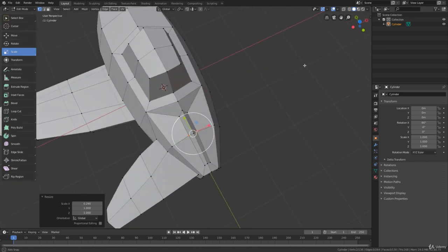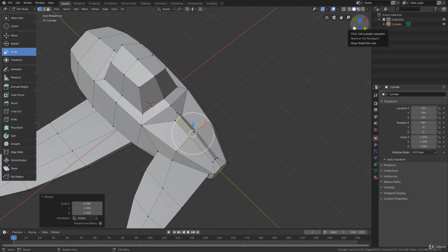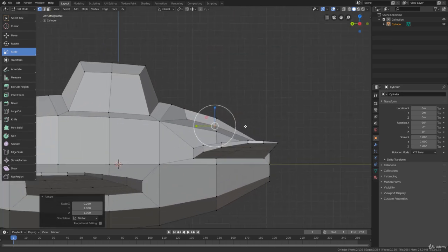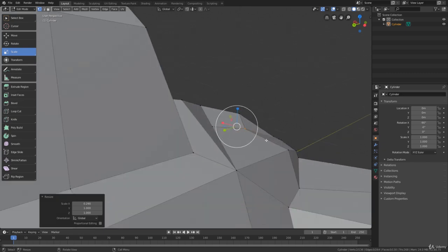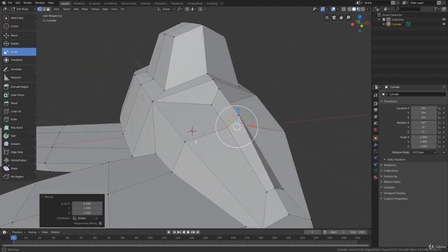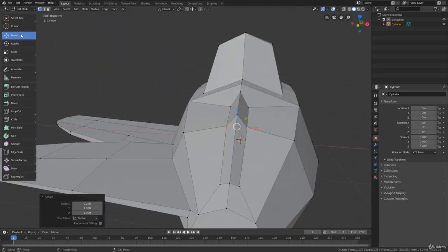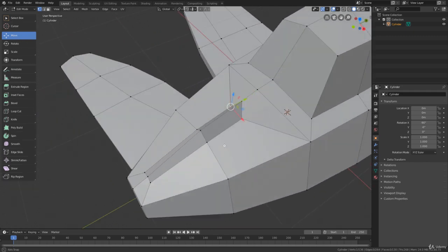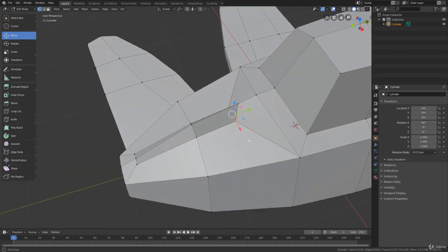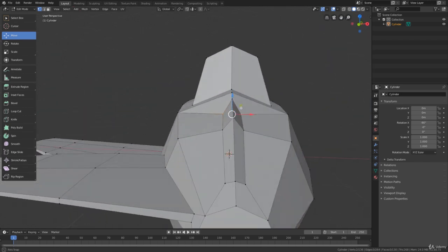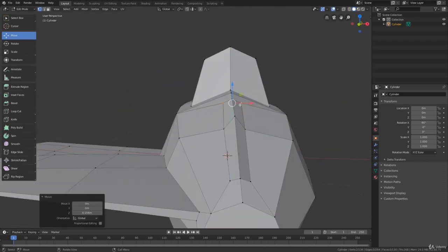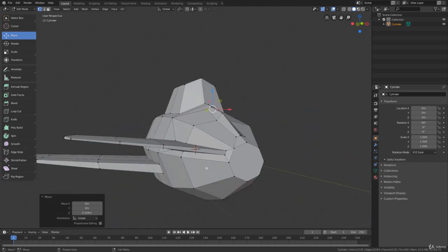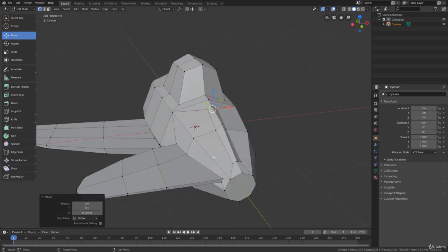Looking from the top, this shape is nice, but if we rotate the view, we will see that this form is a bit strange. Okay, so what I need to do to make things right here is to activate the move tool and move those pairs of vertices by selecting both and moving them up a bit so that the shape is straight as the original faces.